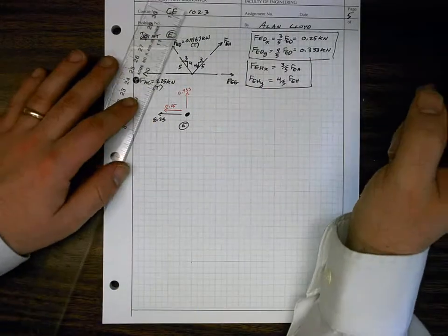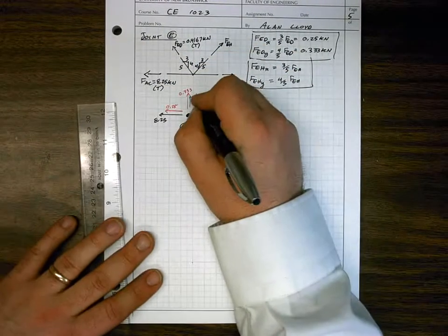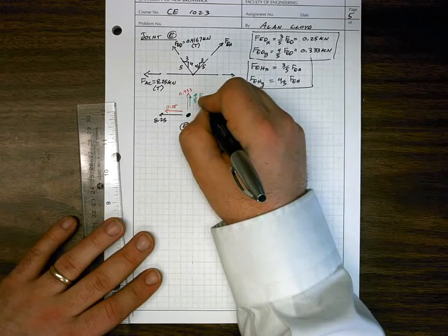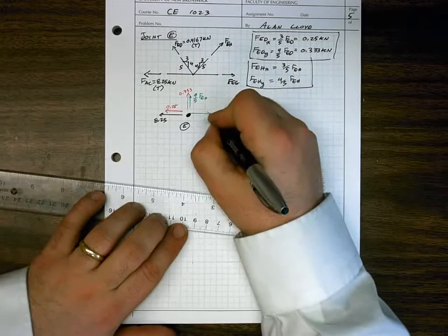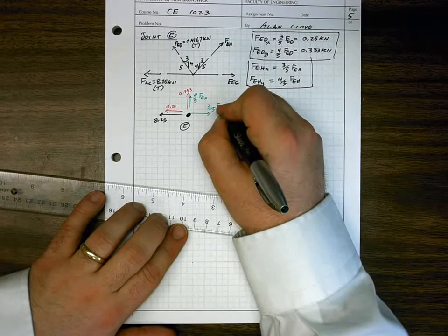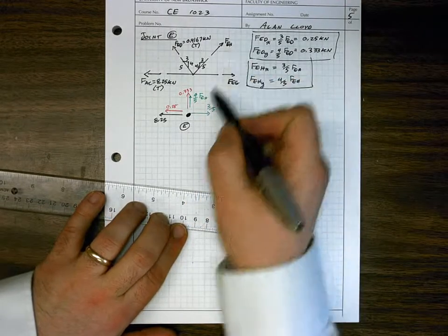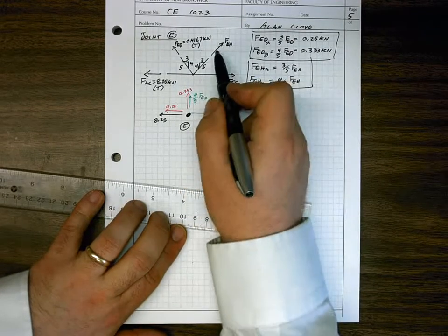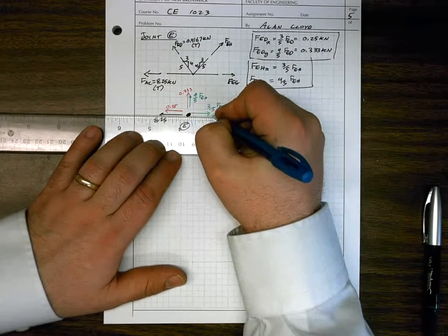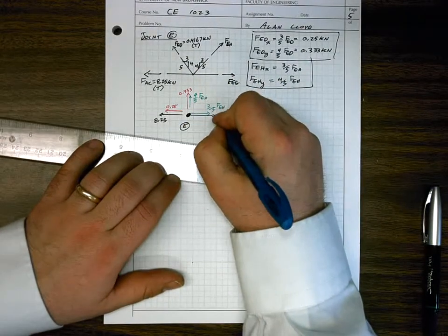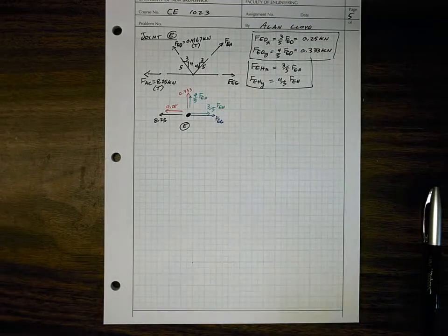We've got a 4/5 FEH, and we've got a 3/5 FEH. That's the x component and the y component of FEH. We know their directions to the right and up based on the direction of FEH. And we've got one more force here. We've got force FEG. That's already in the x component completely, so we don't need to get xy components for that.